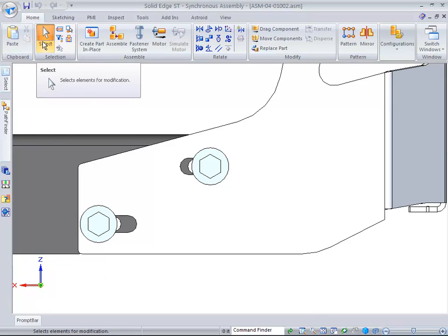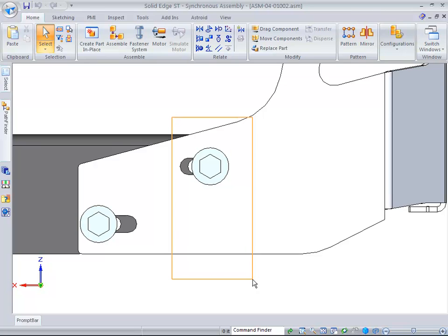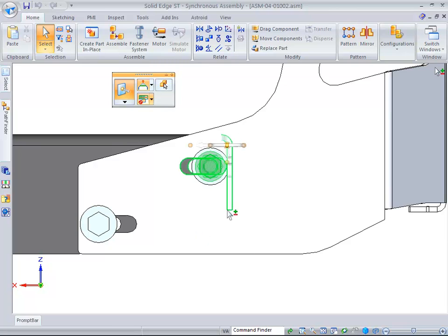Rather than move the mouse up there and go through that operation, we made the keyboard shortcuts, so just select Alt F and then just window select this area. Don't make this too wide of a fence select, because you just want to grab just this area here.